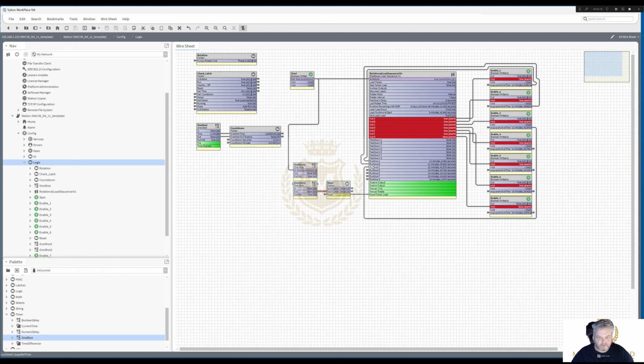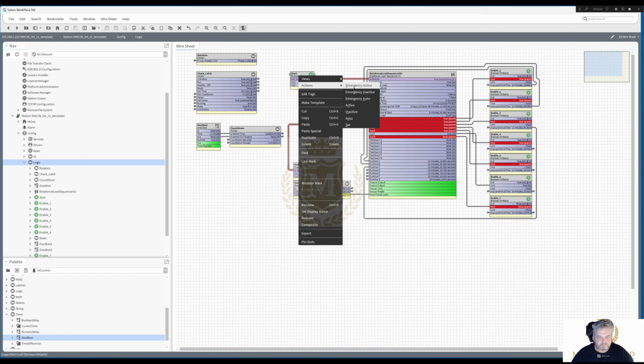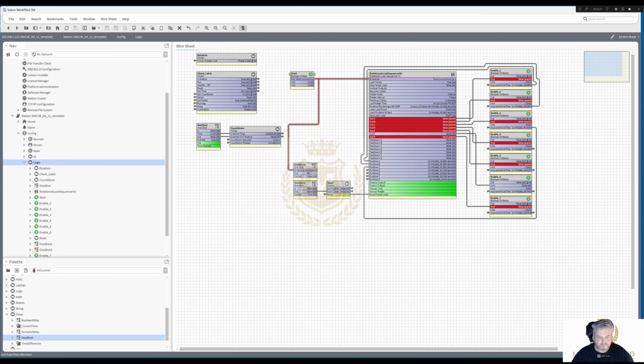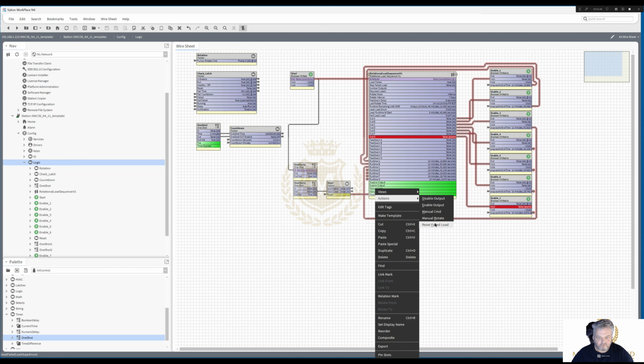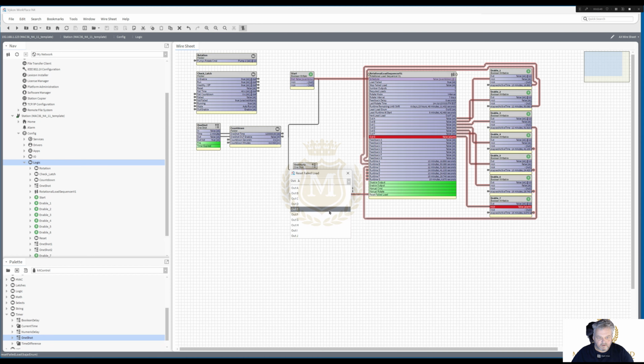They're going back into alarm again because we're getting no feedback. Let me turn that off. Fire a reset again. A, B, C, D, E. F has already reset itself, but G was still staying in alarm. That won't go into a reset at all without you physically changing that. Actions, reset, and select G, out G. Okay, and then that would clear it.